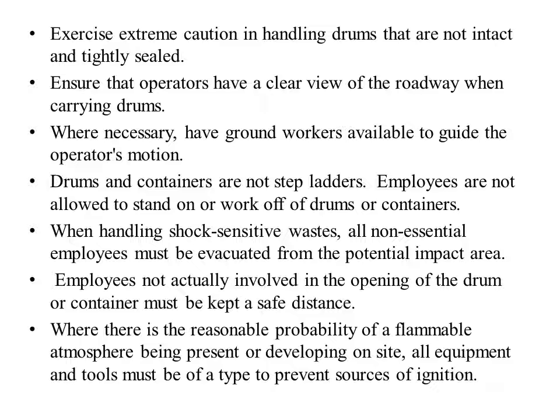And the workers should be told that the drums and containers are not step ladders. That means the employees should not be allowed to stand on or work off the drums or containers. Next point. When handling shock sensitive waste, all non-essential employees must be evacuated from the potential impact area.